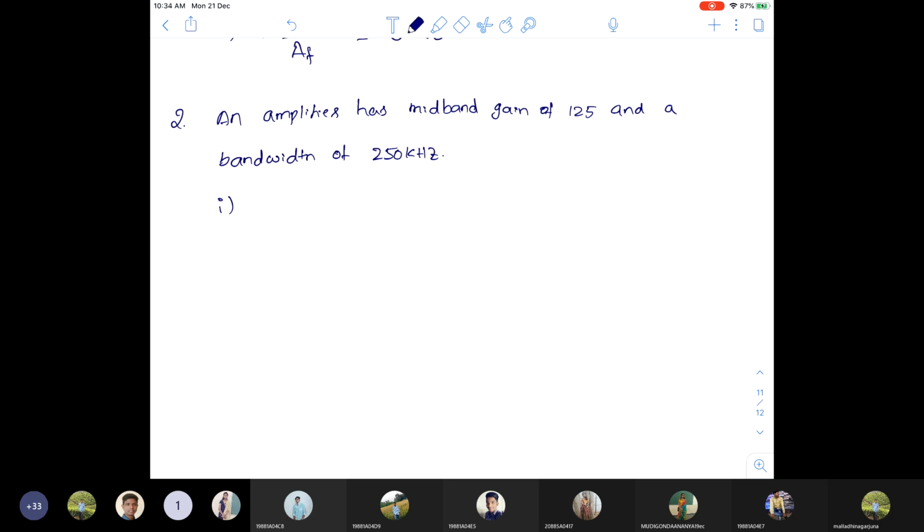If 4% negative feedback is introduced, find the new bandwidth and gain.